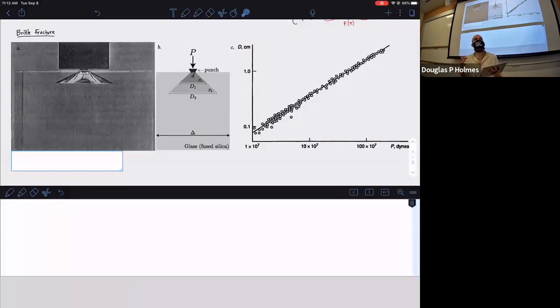So what do I mean by that? What I mean is, if you take a material and you want to know when it's going to break, every material you're going to find, no matter how perfect, is going to have some defects or imperfections on a micro scale. And as you're pulling on this object, those little micro cracks or nano cracks are going to be growing in length. And that's the nonlinearity. You now have this new boundary that you weren't really thinking about inside the material that's growing. And this is what leads to this material fracturing.